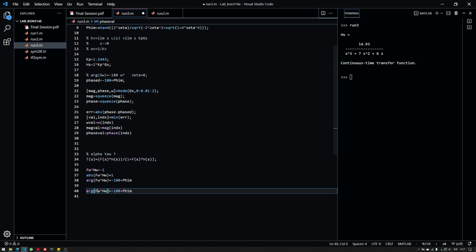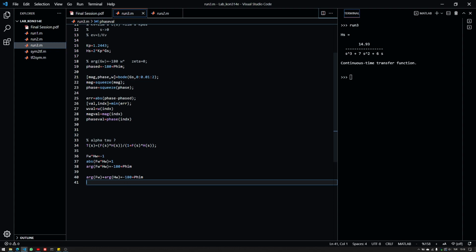Now, I've also talked about the fact that we can expand this argument such that this is the equation that we have to consider. Usually, the argument of the controller is 0 for p-type controllers, and this term vanishes, and then we look for the bode plot and look for this angle condition.